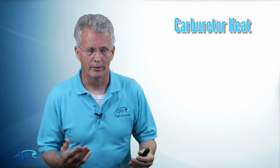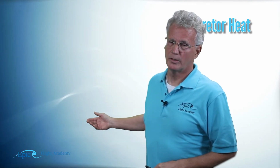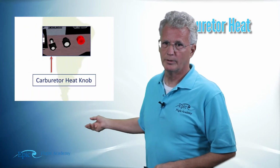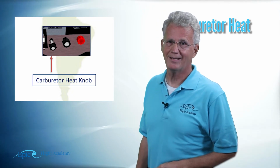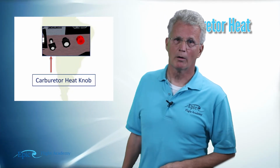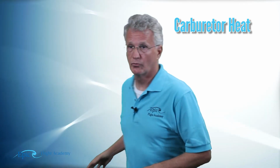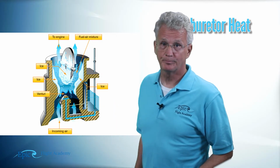Lo and behold, your flight instructor will introduce you to something called carburetor heat. Now, if you take a look at this diagram, you see the red mixture knob on your right, the black throttle knob in the middle, and a small square black one to the left. That is carburetor heat. What carburetor heat does is allows warm air to flow up through this Venturi and melt that ice.